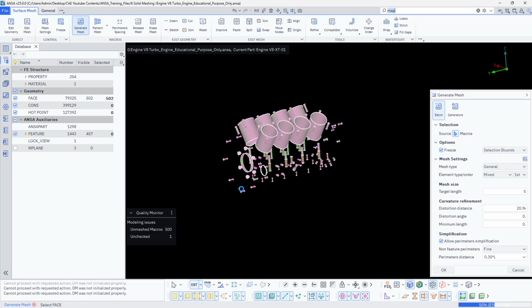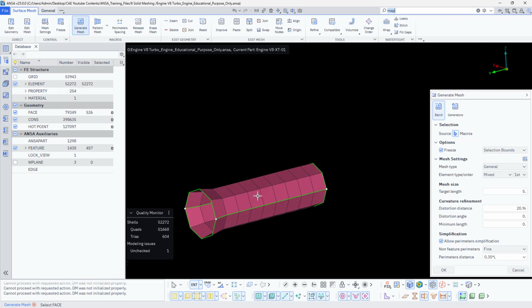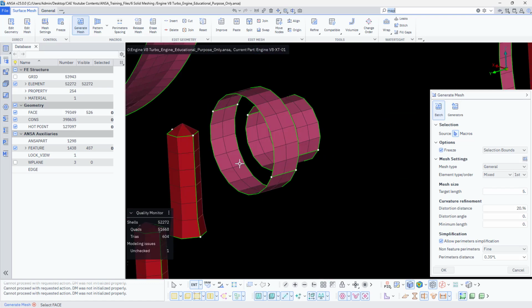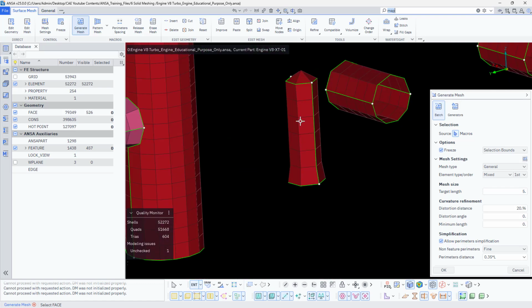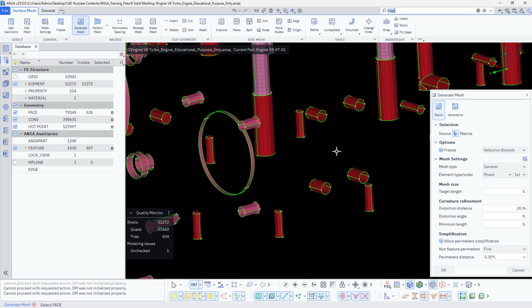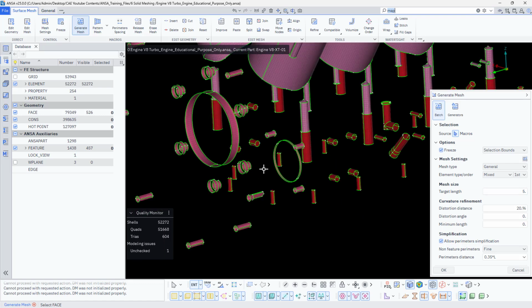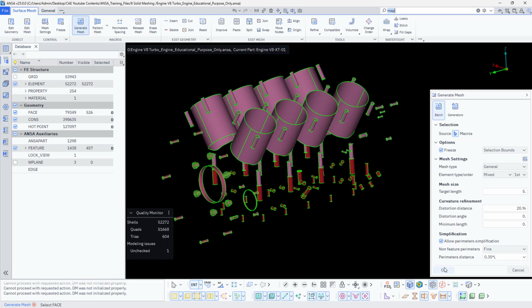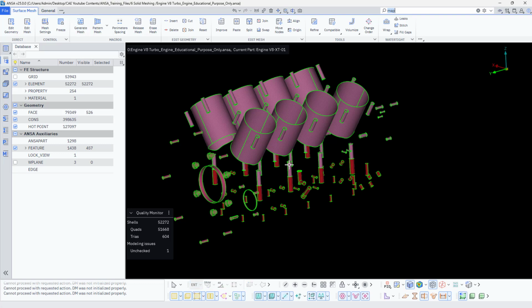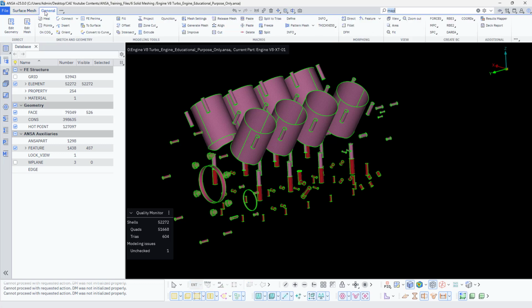So it is properly captured with the 5 mm, no issues. And if you have the holes with less than 5 mm, you can just mesh with 3 mm or 2 mm, and you can freeze it. Okay, so let me just show the same. So I'll just click OK. I would like to freeze these, so you can use the freeze.